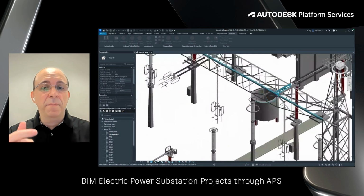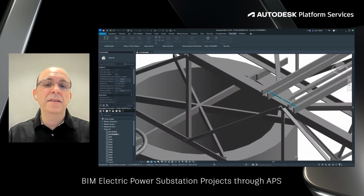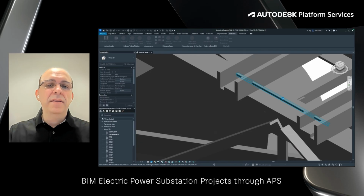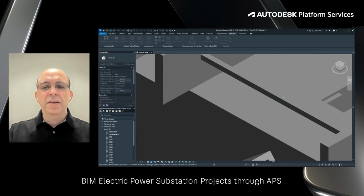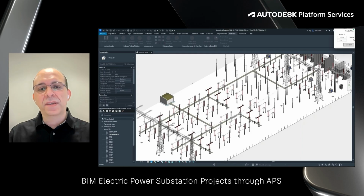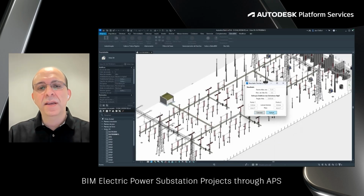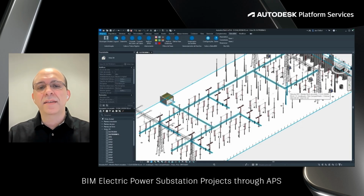And then there's going to be a bunch of calculation behind the scenes in the plugin, so it can calculate again the span and design the perfect points of this curvature. What the plugin does is trace the cable passing through every single point calculated. So we have the perfect curvature of this cable. And again, this is very important to see if it's going to be too close to other electrical equipment. That would be a violation and a risk. So they need to have this precise design.